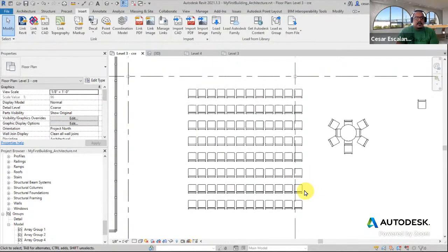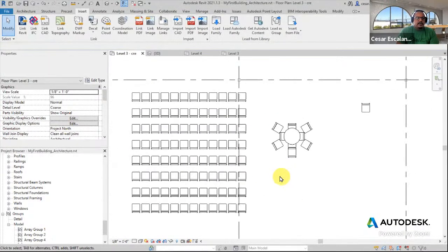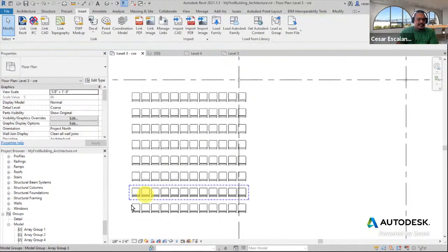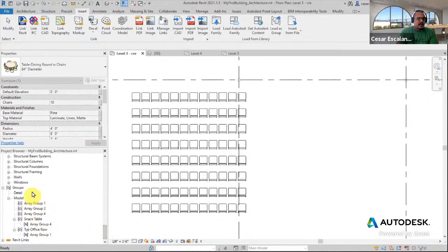But I'm glad that you brought that up, because when a project is infested with groups, it's going to grow in size a lot. And when it grows in size, your BIM manager, who does BIM maintenance or Revit maintenance to the file, will have to convert a lot of these model groups into families, and that process is very tedious and very long.